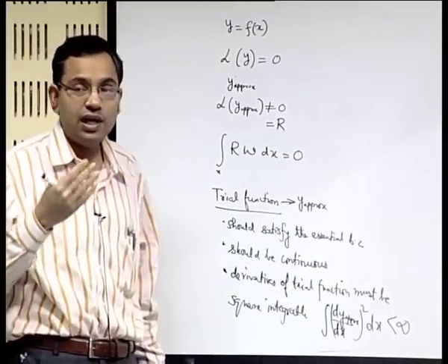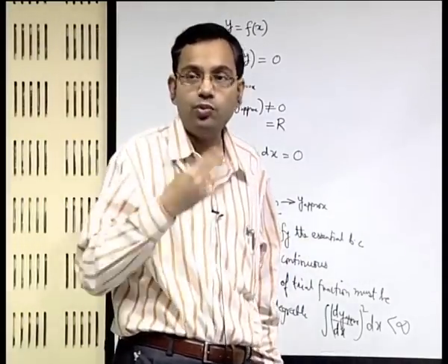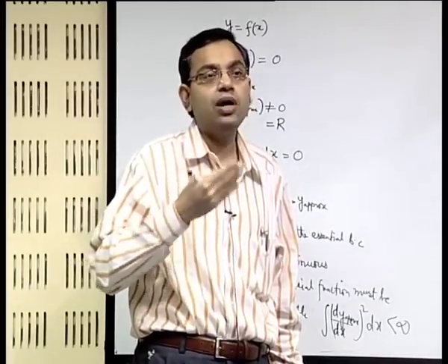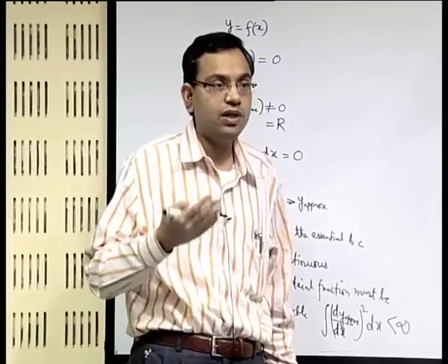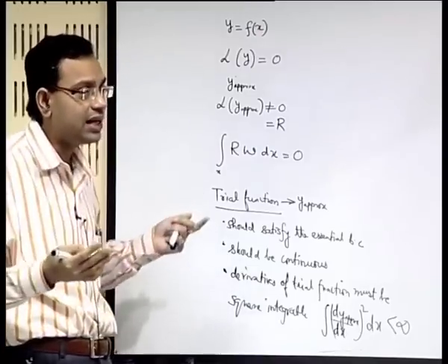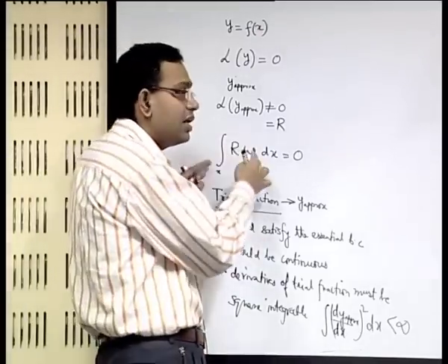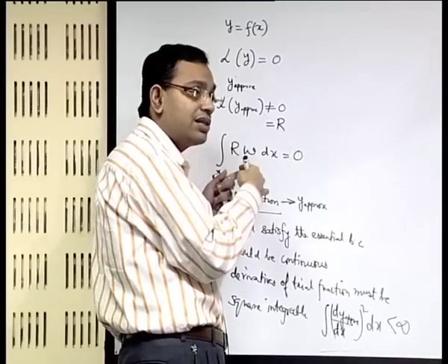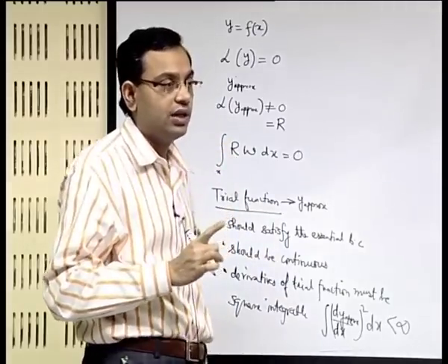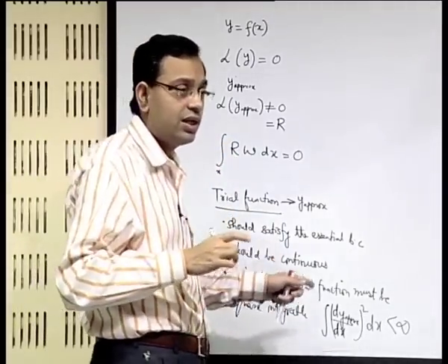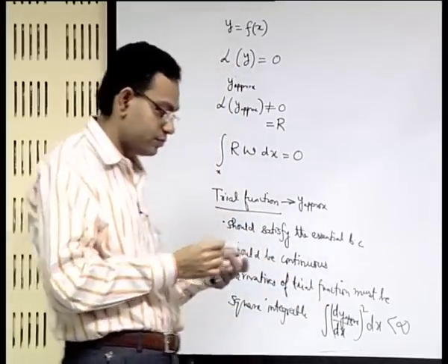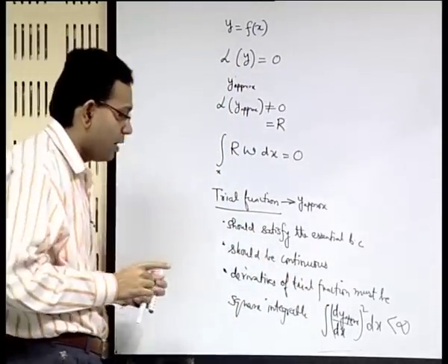parts. So, the variational formulation is sometimes called weak formulation, because you weaken the requirement of the order of the continuity of the approximating function. But if you do not employ that as a strategy and simply do the integration without integration by parts, then obviously you require the continuity up to the highest order derivative. So, it is not the first order derivative for a second order problem, it is a second order derivative for a second order problem. This we must keep in mind.